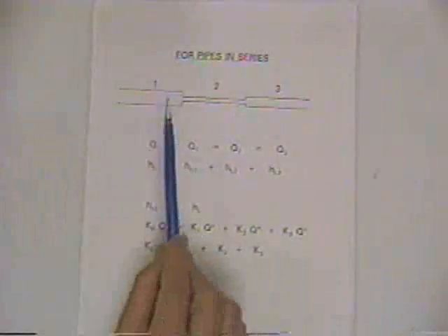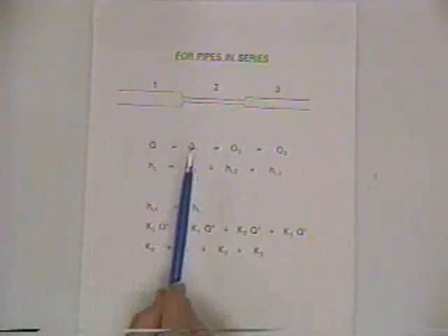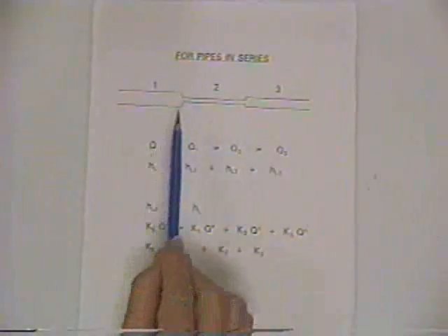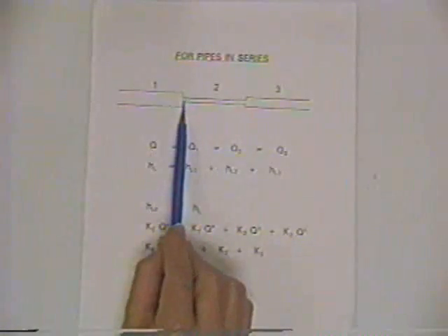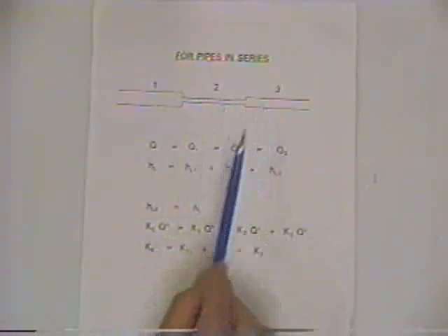And so if you had more than one pipe, the pipes could be either in series or in parallel. If you've got pipes in series like that, looking at head losses and discharges, just due to conservation of mass, the continuity equation, whatever comes out of this pipe goes into that pipe and so forth.